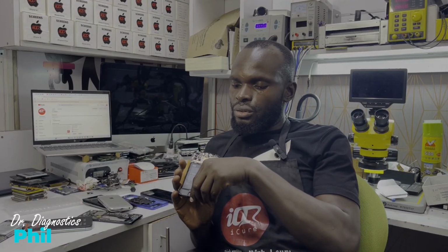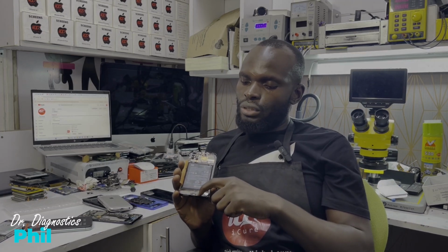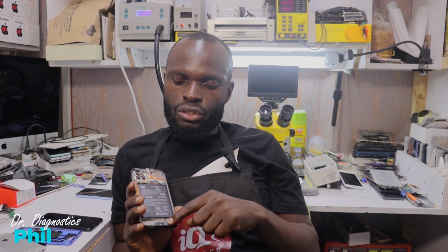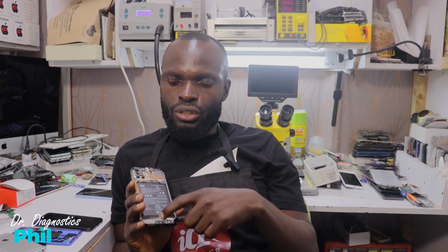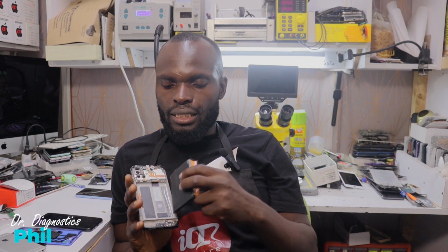It's the one that gives out sound, music, whatever you're playing on YouTube, you're listening through this one. Whenever your phone rings, this is what produces the sound. It is connected to this subboard and to this cable. Then all the information is obtained from this motherboard. So there is a continuous connection from this ringer to the subboard, to the flex here, to the board. The flex that joins the subboard to the main board is called an FPC, a flexible printed circuit.